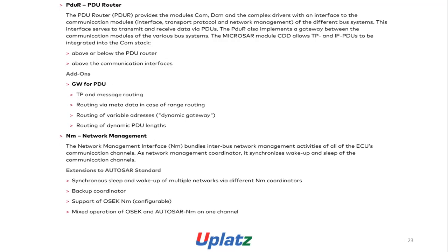network management activities of all of the ECUs, communication channel as network management coordinator. It synchronizes wake up and sleep of the communication channel. Extension to AUTOSAR standard: synchronous sleep and wake up of multiple networks via different NM coordinators, backup coordinator, support of OSEK NM, configurable mixed operation of OSEK and AUTOSAR NM on one channel.